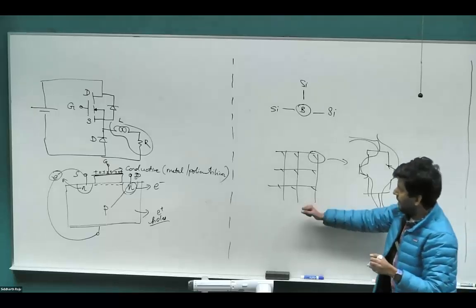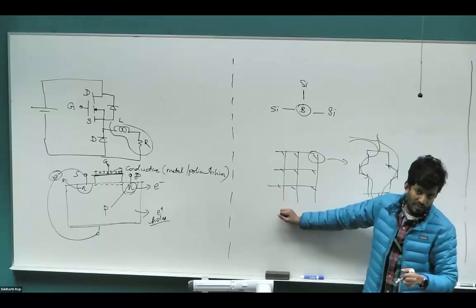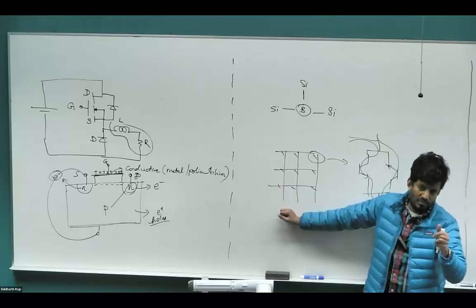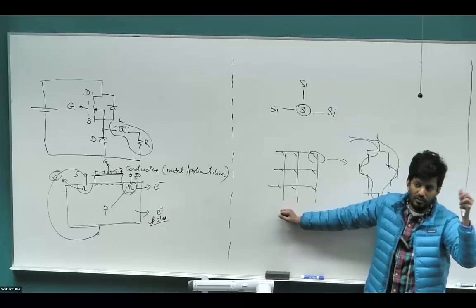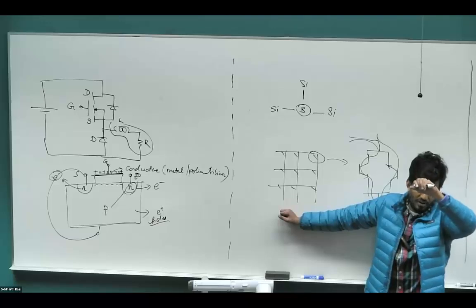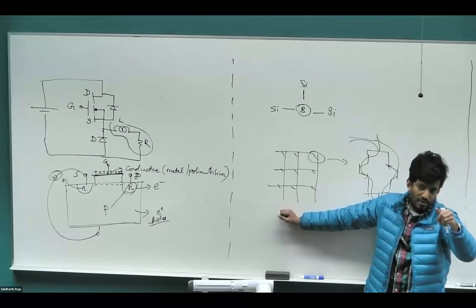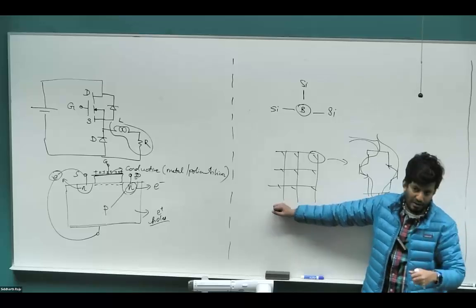Right? So the way when this would be applicable is, let's say I have a grid connected motor. Sometimes it's going to behave like a motor, but sometimes you want to regenerate the power. For an example, when we had the elevator case, right? When there is a sufficiently large load on the carriage and people are going from a lower floor to a higher floor, you're putting power into the system. But when the carriage is coming from a higher floor to a lower floor, you can actually extract that energy and give it back to the grid, right?